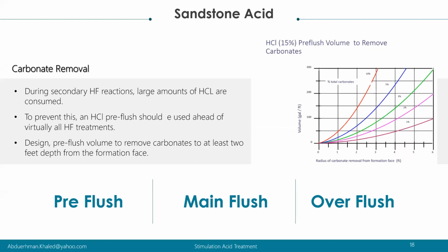The 12% HCl and 3% HF recipe is not used a lot anymore, but mostly these days we use about 13.5% HCl and 1.5% HF, and even less, especially if we have feldspar around. So we'll go down to 9% HCl and only 1% HF. According to that, you will decide what is the best recipe to prepare.